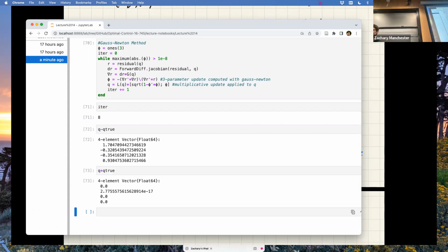Generally, this is fine and doesn't cause any problems. But if you are a little bit naive about how you, for example, write down your loss function or your error in your feedback controller, you can run into problems because of this. There's this famous thing called the unwinding problem. If you write down a really naive feedback law on a quaternion, and say I'm trying to do feedback on Q, and I have a Q ref, if my state estimator all of a sudden flips it around and gives me minus Q ref, you can have your controller wrap you around like 2 pi for no reason because of this thing. So this is a fun fact to be careful of. There are good ways to deal with this. It's not a big deal in practice. You just have to be a little smart, but that's kind of it. Okay, that's it. Thanks everybody.